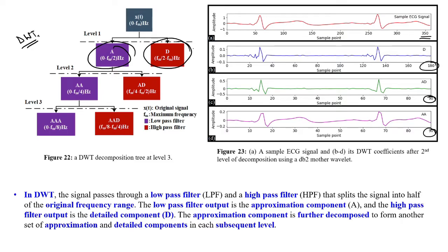So there are two kinds of discrete wavelet transform. The first one is undecimated, which is the original one where we do not take out any signal component. However, in this case, when you go for a higher level of decomposition, and you have a large time domain signal, you will get a lot of coefficients, and it becomes very difficult to store and analyze the data, because the size of the data will be too high.